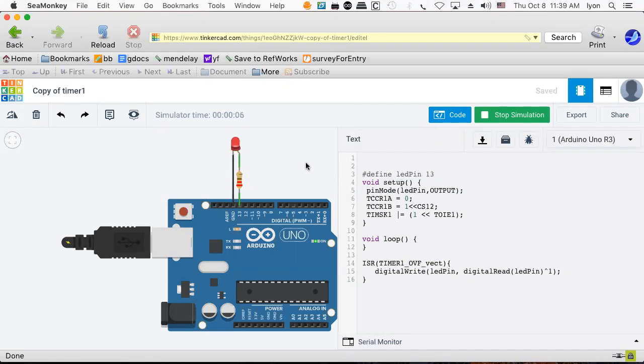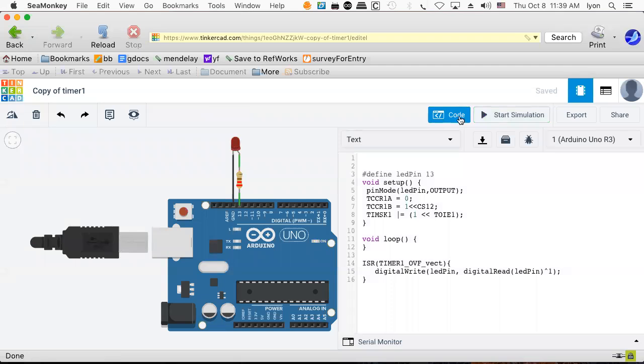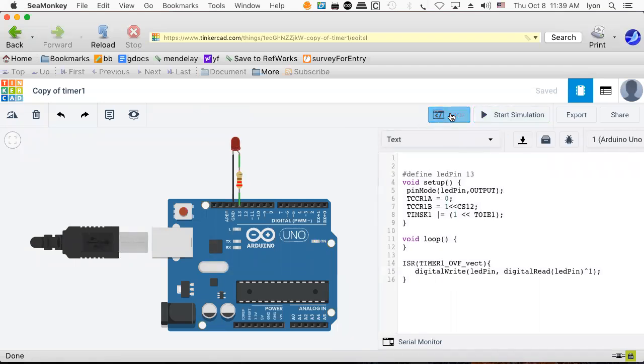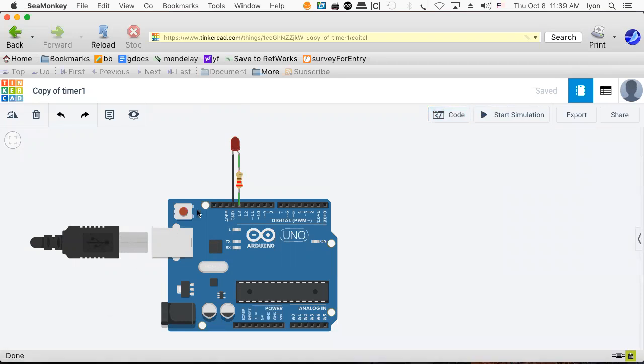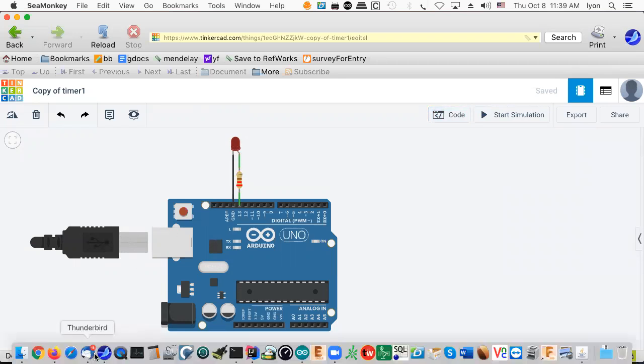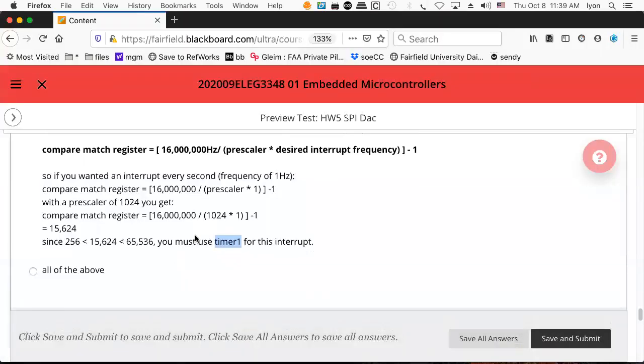So you can have fine-grained control of the timer and then control certain things that go on in the background, while in the foreground you can have your loop running. So in the background, what you could have is your ADC converter pulling in samples, running it through some process, and then in the foreground you can do some kind of, I don't know, fancy thing, whatever that is. So that's a good example of how you might use the timer to do something like make the light blink. You probably want to do other things with it than that, but there it is.